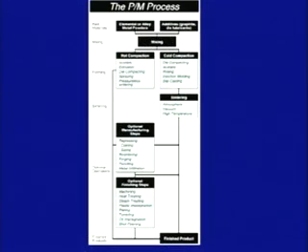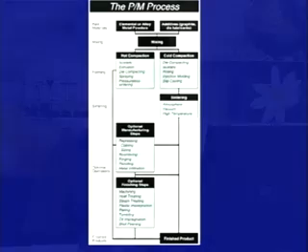Now, this is the powder metallurgy process. Already we have started the discussion with the basic concept of powder metallurgy, which is that we make the powder of the metal. This metal powder is then mixed with different types of additives. These can be die lubricants or some other kind of wax or polymer based lubricants. This process is called mixing or blending. So, we have a metal powder, that metal powder is then mixed with the lubricants, then we get these two things together. Then finally, we press this mixture into a die with the help of a die and a punch. Now, this can be carried out either in a hot condition or in a cold condition.